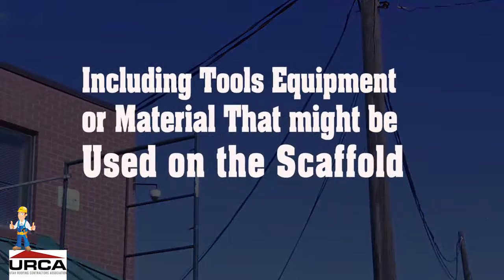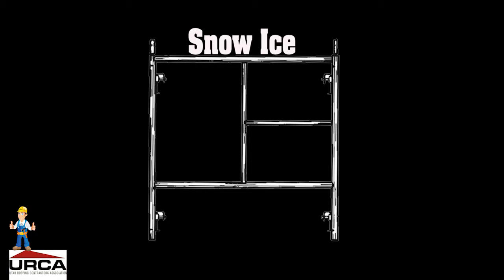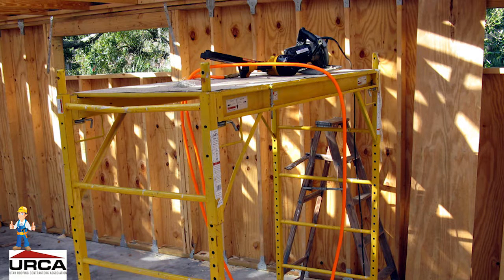This distance applies to any part of the scaffold, including tools, equipment, or material that might be used on the scaffold. Check the clearance prior to erecting the scaffold. Do not work on snow or ice-covered platforms during storms or high winds. Portable electrical equipment such as tools, power cords, or generators can also pose a serious electrical hazard for workers on and/or around scaffolds.